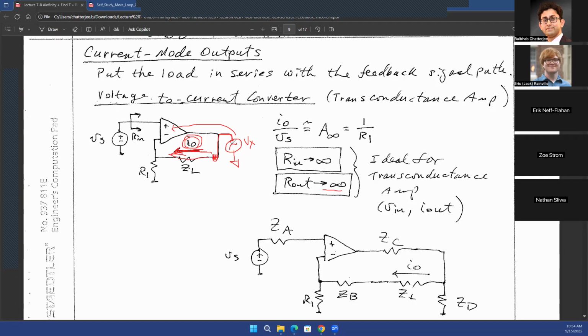If you connect your Vx at the input, that will not work, because you're trying to find the output resistance. But keep in mind, what is the quantity of interest? Is it a voltage or a current? And where am I looking at that voltage or current? So you have to put your test source at exactly that same point where you're interested in finding the resistance. Okay, thanks.